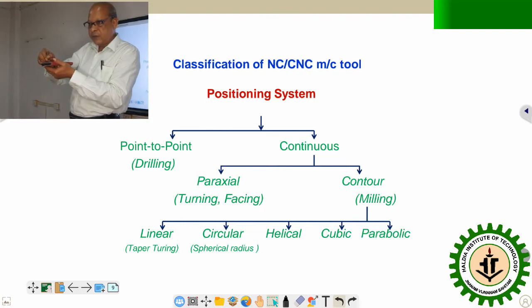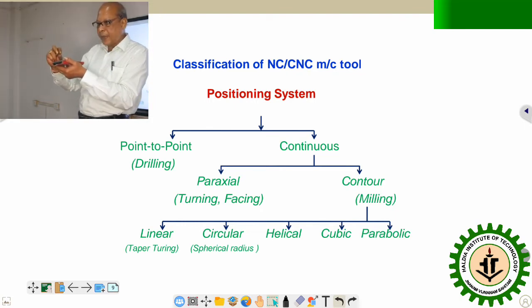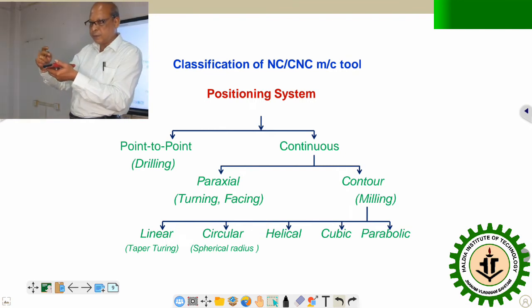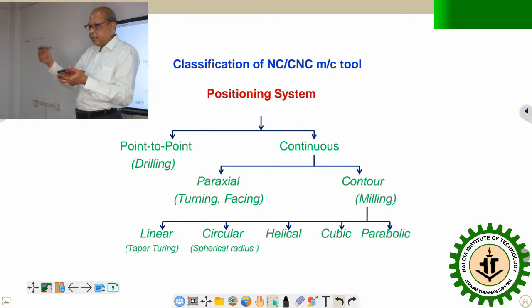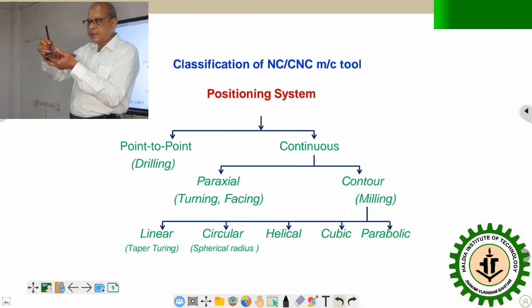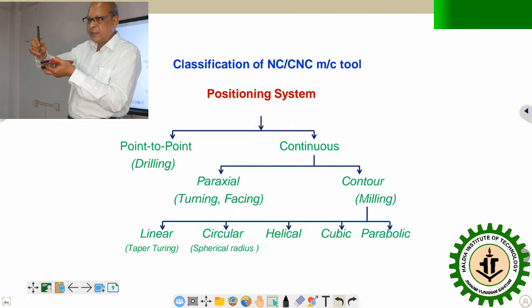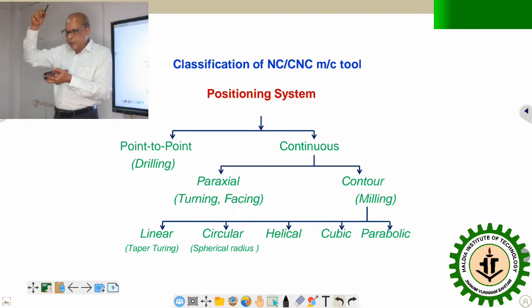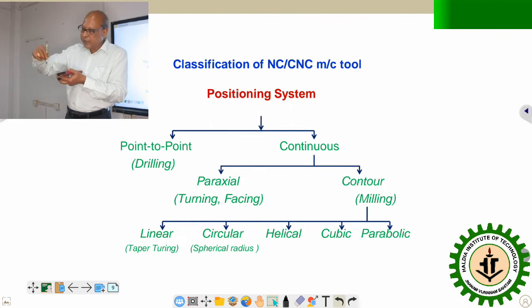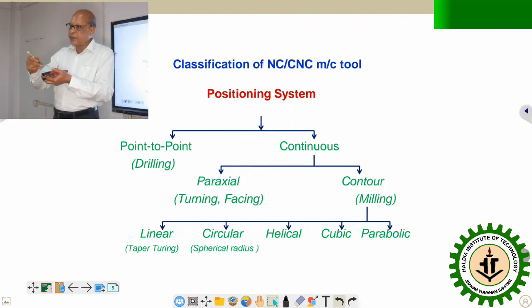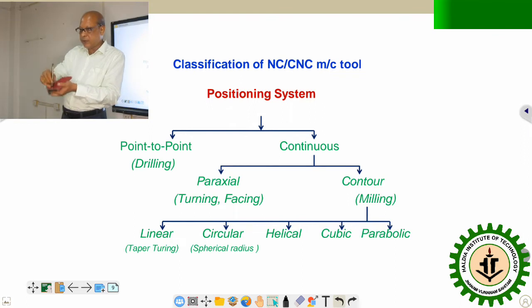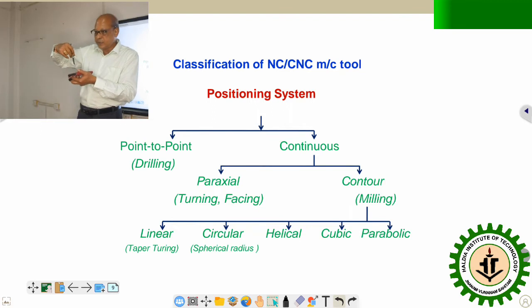first hole, but keeping a margin of some gap from the top of the job so that it will not collide initially. So the objective is to bring the drill center point exactly above the coordinate of the first drill location. Once it reaches this point, then in the subsequent movement, with rotation and feed, it will keep penetrating the job according to your desired depth. It will enter into the hole while moving, then it will retract by reversing its rotation,